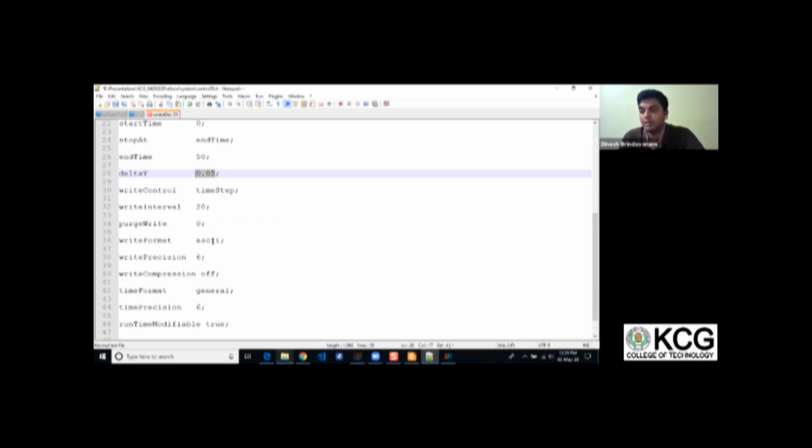Some basic geometry you can do, but if you want to do complex geometry, then at least you should have learned a basic simulation in OpenFOAM. So first you initially start with some basic simulation like how I'm doing. Later you can do the mesh. If you want to do very complicated geometry, there is something called snappyHexMesh. Again it is a command line text file which you need to tweak to get your work done.